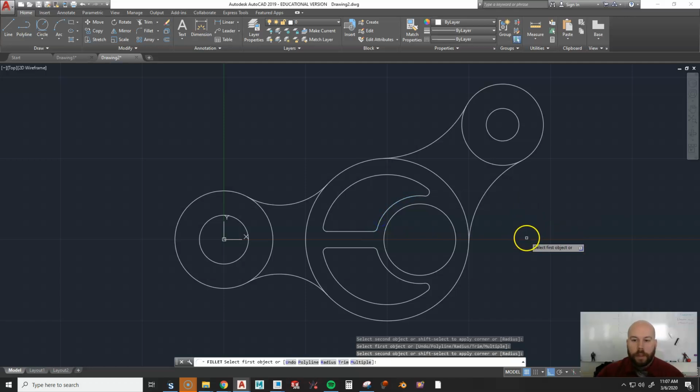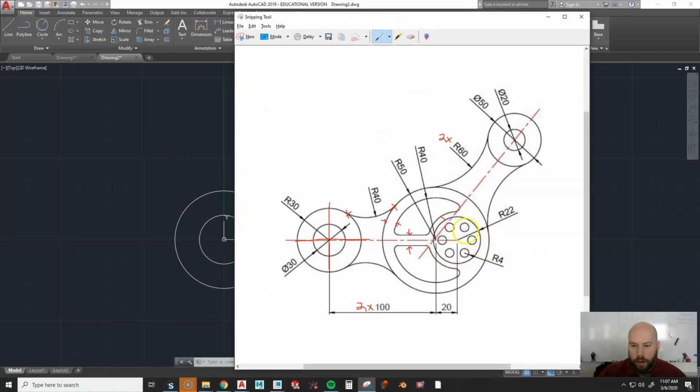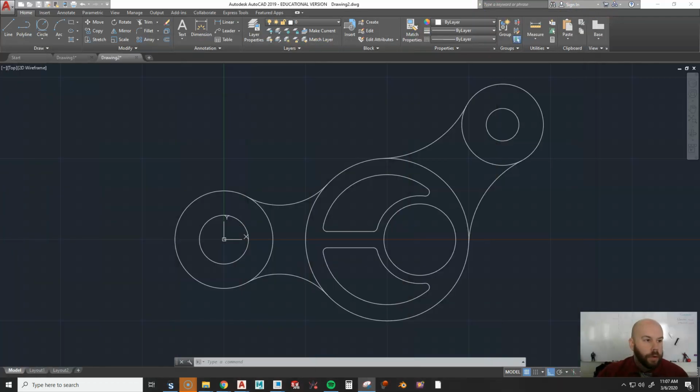and that one. Okay, now the last thing I have is that circle pattern. Now again, we can see there's no diameter here. So I'm going to use my best judgment, which may or may not be right. And I'm going to say that these are, let's see, maybe about the same width as that. So 5 from there, which means if this is 22, then we need to take away 5. That brings us to 17. If the radius of these are 4, that brings us to about 13. I don't know. Let's try a 13 diameter. We'll see. I'm really thinking out loud here, folks.